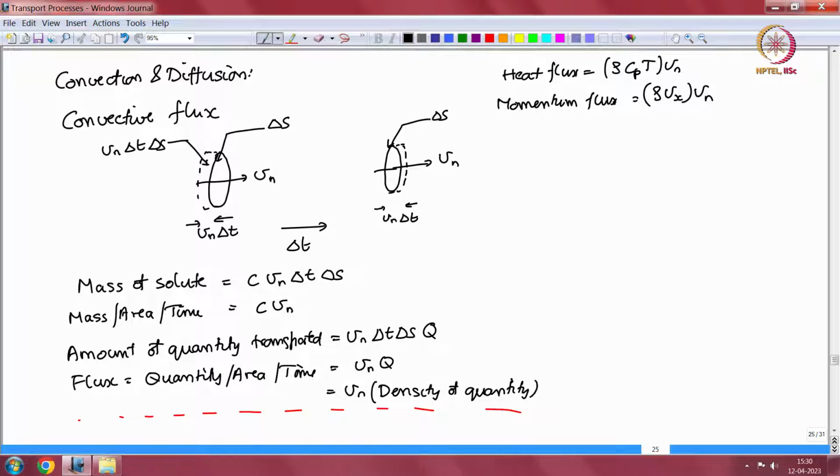In the last lecture, we were discussing the definition of dimensionless groups as either dimensionless fluxes, ratio of convection and diffusion, or the ratio of two different kinds of diffusivity based upon the characteristic length, velocity scales and the diffusion coefficients. So, I defined the convective flux for you as the product of the normal velocity times the density of a quantity.